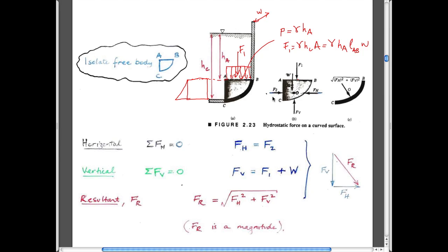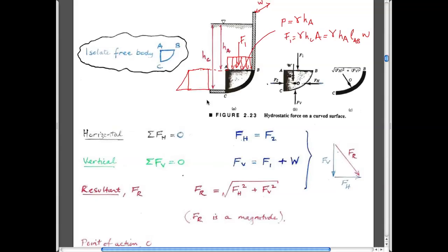We want to know what the magnitude of F2 is. So we can think about this distribution, but I guess what we know from this distribution is that the resultant of this fluid pressure isn't going to be working at two-thirds the depth anymore, right? Because we have this distribution. And so we just need to note that that's the case. We can calculate what that is, I guess I don't do it here, but we can calculate that from our expression for YR, which is equal to what?